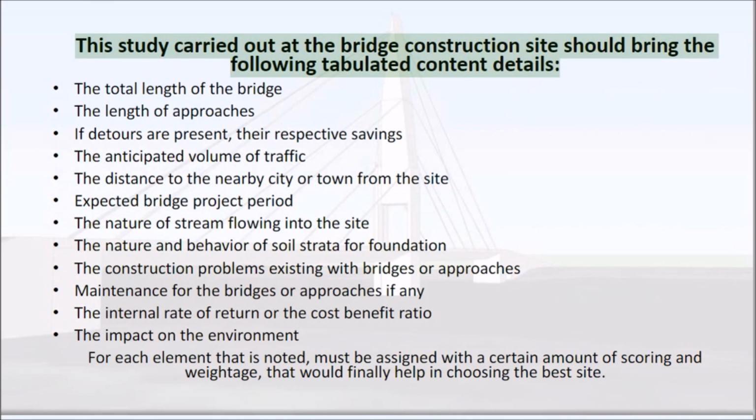This study carried out at the bridge construction site should bring the following tabulated details. The total length of the bridge. The length of approaches. If detours are present, their respective savings. The anticipated volume of traffic. The distance to the nearby city or town from the site. Expected bridge project period.